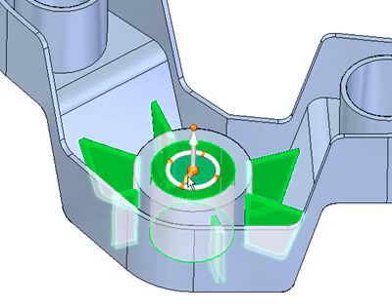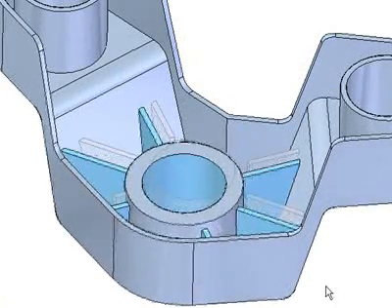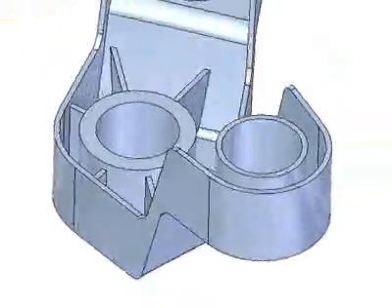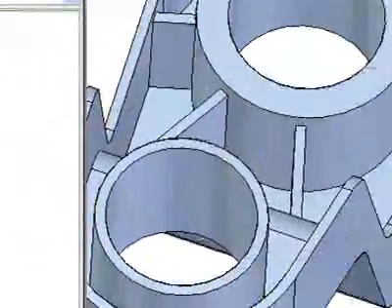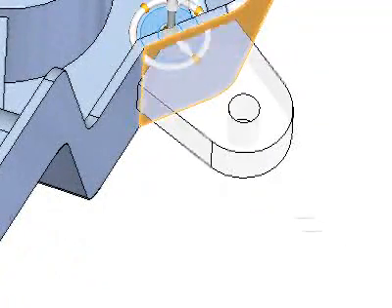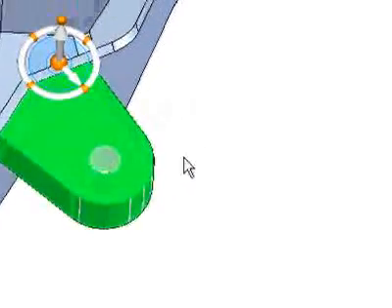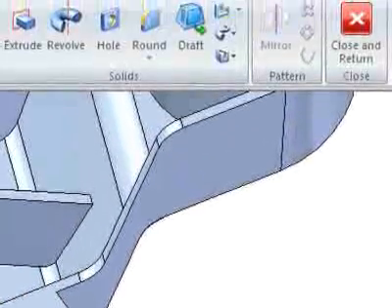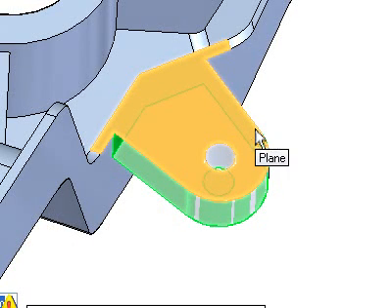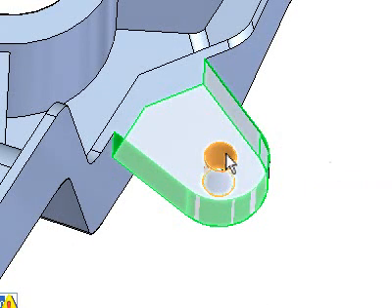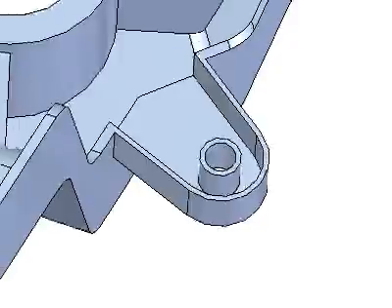Another powerful capability of Solid Edge with Synchronous Technology is that you can add as many thin-wall operations as needed. This capability eliminates the amount of pre-planning engineers need to invest in making flexible models that can accommodate last-minute additions and future changes. For example, the initial requirements didn't call for a mounting foot, so it wasn't added. While it can be added in a history-based system, reordering would be required to position the new feature before the shell so it gets hollowed out. Because you can add additional thin-wall operations in Solid Edge, users have total design flexibility by making adjustments along the way without having to worry about managing a complex sequence of steps.